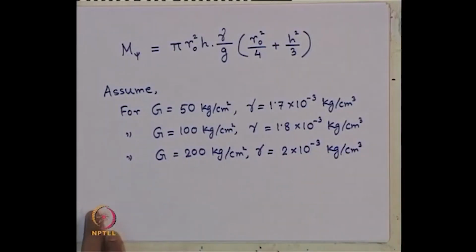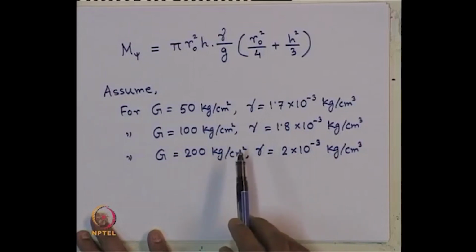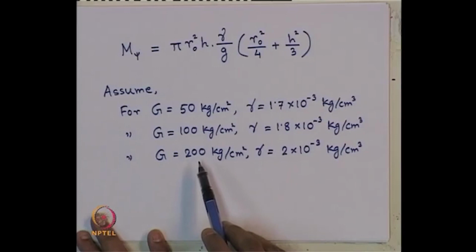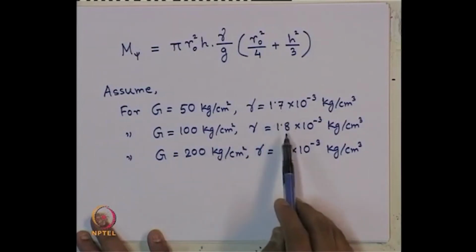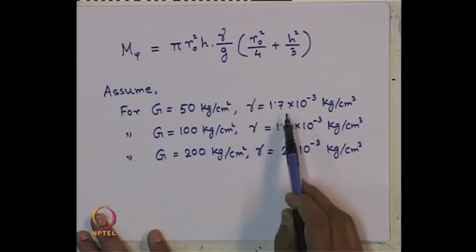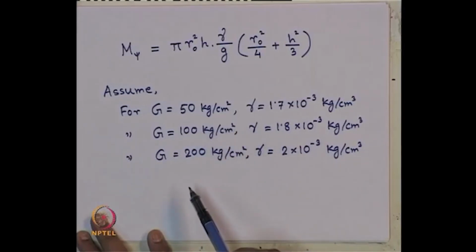These are based on how we have assumed this gamma value, a reasonable value we need to assume. As g increases, we know it is a stiffer soil. So, that is why we are using standard unit weight of soil in increasing order as the g increases. Okay.